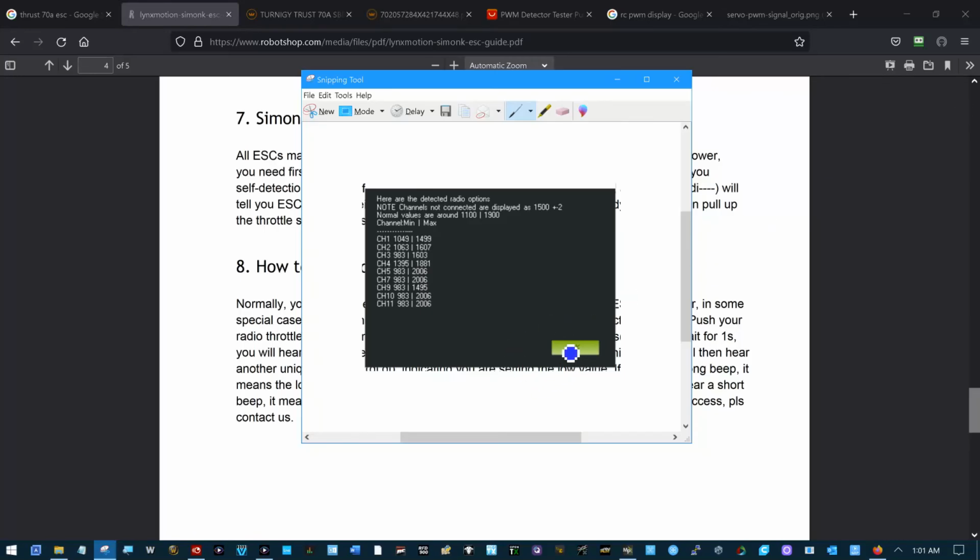If I have trouble calibrating my ESC, I can find a spare RC receiver in my shop, go straight up with nothing but an RC receiver. If it's a SBEC or a BEC ESC, you're going to have a battery elimination circuit in it. You're not going to need a battery to make all this work. The only thing you're going to have to do is plug that ESC into the RC receiver, and it's going to supply power for it and ground and make it power up as soon as you plug in the battery.